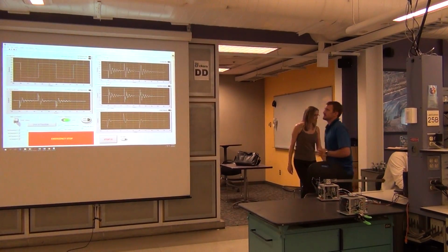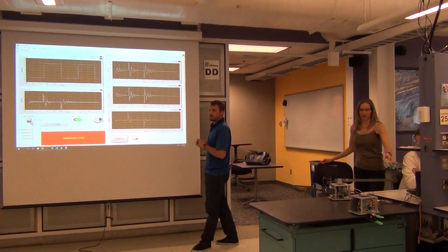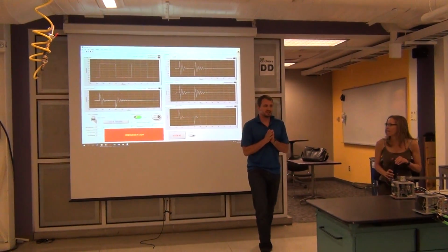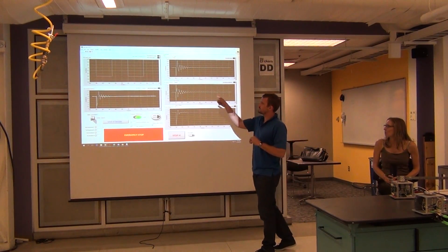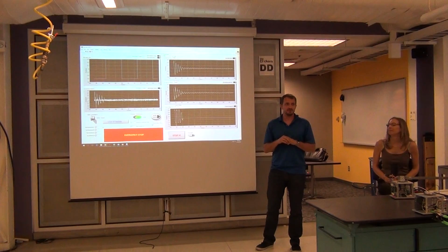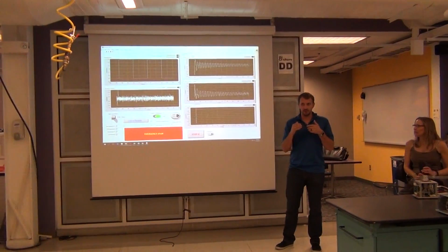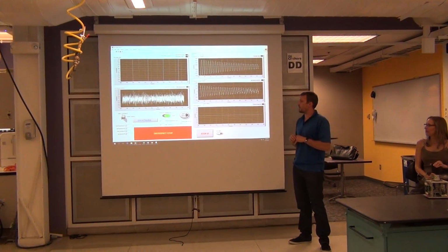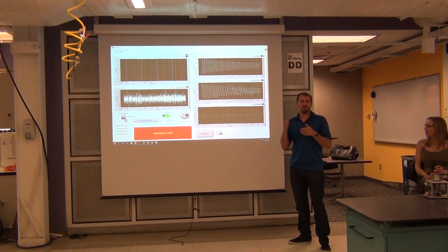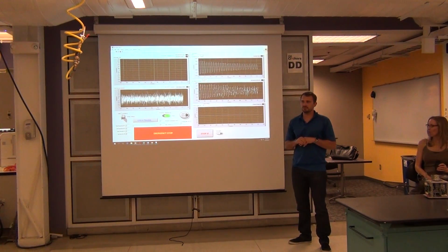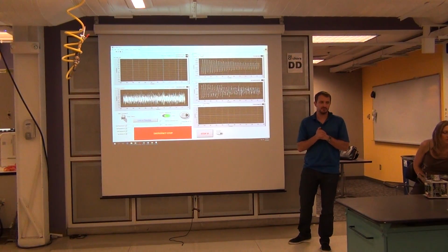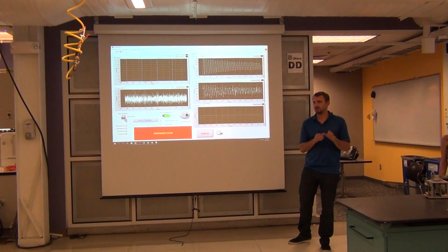So one other limitation we have here has to do with the derivative and how that's being calculated. We're taking the derivative just from the position sensor. So you can see once this chart zooms in a little bit that there's some noise on that. When you take the derivative of the noisy signal, that noise basically becomes amplified or carried over onto the derivative portion as well. So then when you apply a gain to that, your velocity contribution could become noisy, and that is another contributor for the physical limitations here with regards to the instability, with regards to the noise. Okay? Does that make sense?